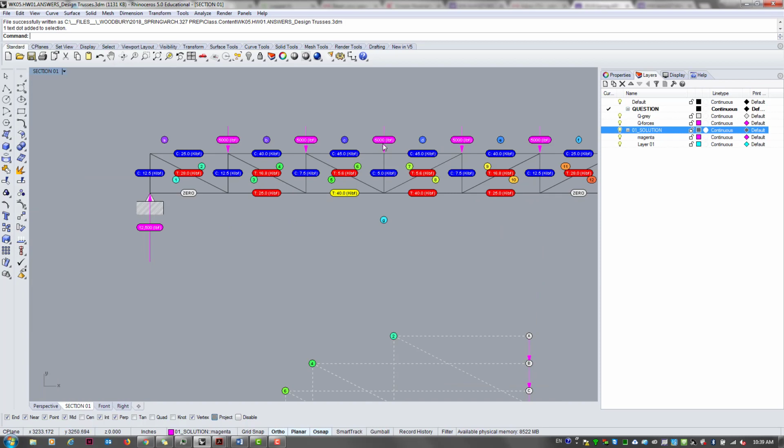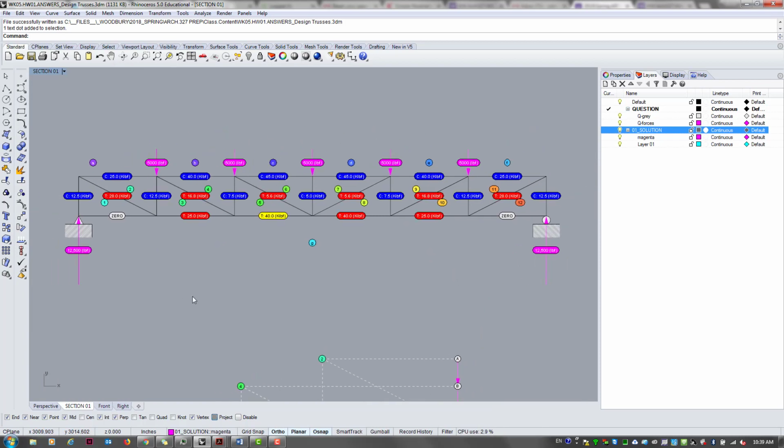So the loads are going to be the same, therefore the reaction is going to be the same. So how are we going to do that, right? Probably the problem is that this tension was too much, and it's exceeding what's allowed for the particular member or something like that. We've also learned already, right? Making the truss deeper decreases the internal forces a lot, right?